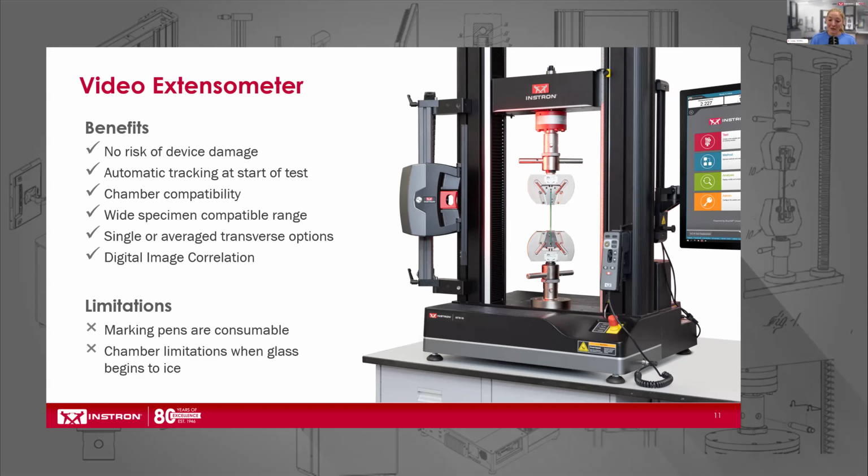So you need to make sure, if there is humidity in your lab, is your window fogging up and freezing over? Because if that's the case, then our recommendation in that situation would be to use a contacting extensometer like a clip-on, because you really want to make sure that you're not compromising your data collection in those situations.